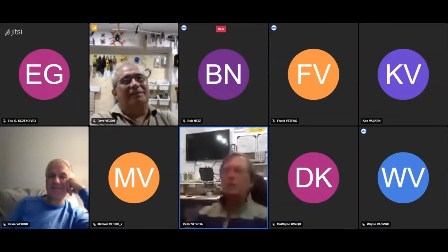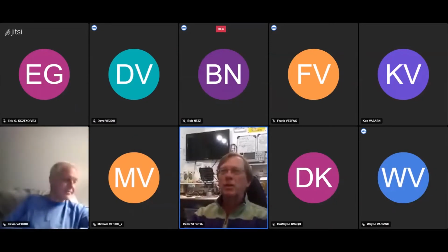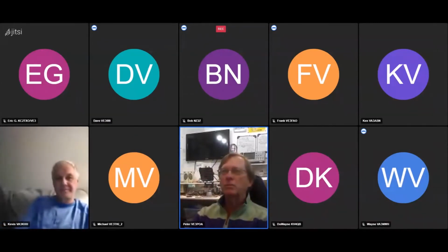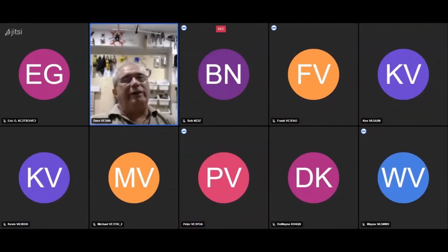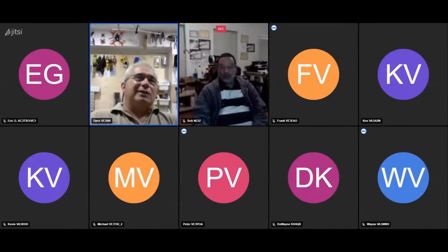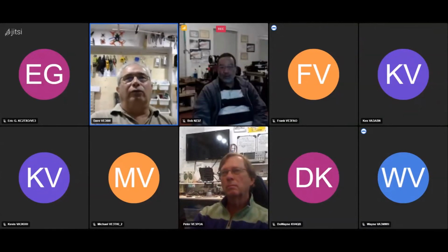I guess the bottom line, Dave, is what do you see on the end? Is it interfering with anything as it goes further up the chain or down the chain? Yeah, see, I'm just tracing it through and I'm seeing 40 dB down. And 40 dB, I think that's a lot, because if you look at the spec for Industry Canada for harmonics, it's 44 dB down. So 40 dB down on your traces, I think is perfectly acceptable.